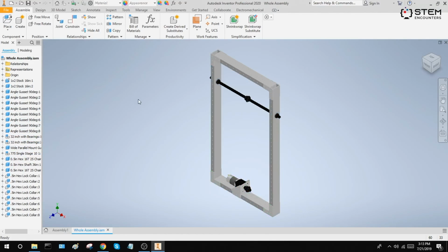So to summarize, always when you click the home button, have your assembly oriented so that homing your view gives an appropriate view of the entire assembly. Second, if the orientation is off, constrain your assembly to the appropriate planes, make as many constraints as necessary, delete those constraints, and then ground one part of the assembly. And if the assembly is constrained correctly, nothing should fall apart.